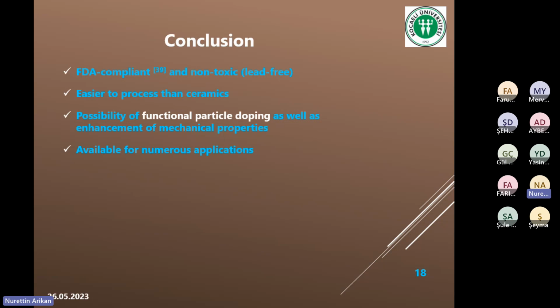However, I should highlight again, it will wear out the nozzles of your 3D printer, since piezoceramic particles are very abrasive, and even though they are homogeneously dispersed in the polymer matrix, it will still probably wear out any nozzles, and even hardened steel nozzles will suffer from their highly abrasive behavior from time to time.